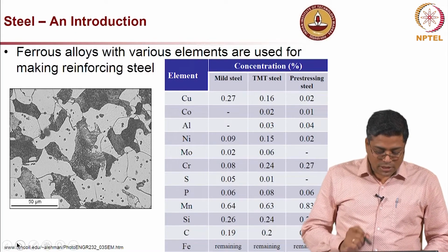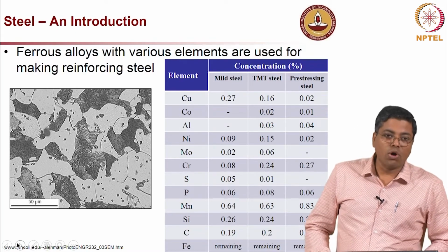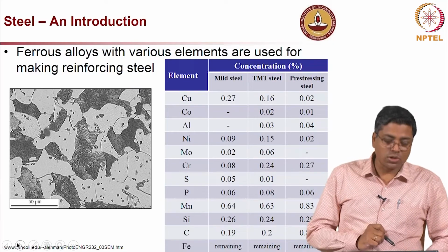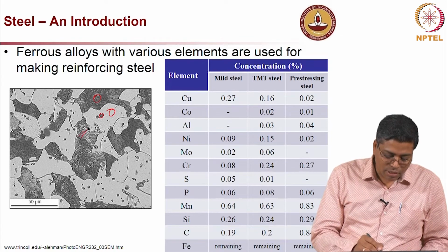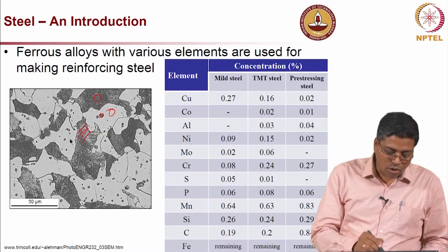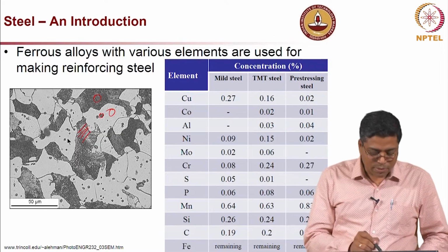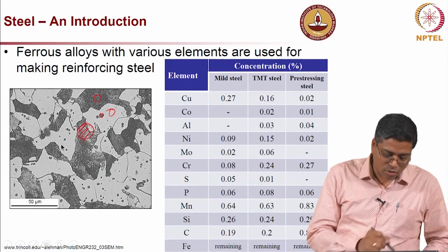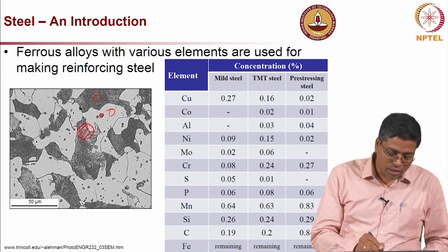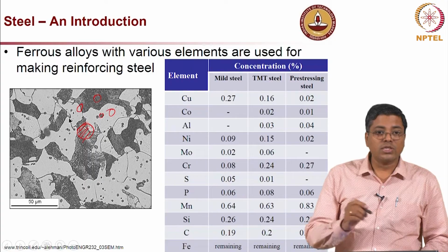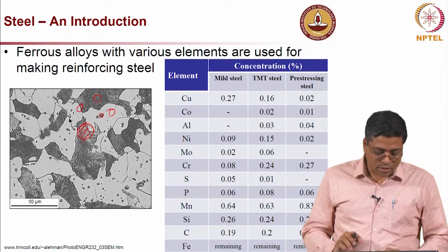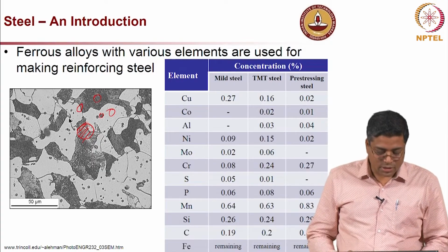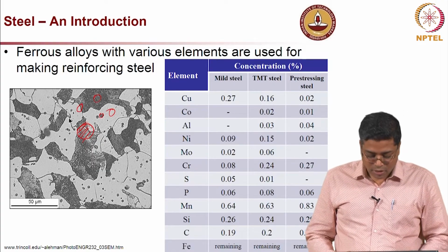Now, when you look at steel, usually we think it is a homogeneous material, but if you look in a microscope, this is how it looks. So, you have these different phases in the same steel, and you can see some lamellar structure here. All of these lead to some kind of local corrosion cell in between. So, one of the phases might be corroding in preference to the other, and that is what metallurgists like to modify so that we can have better quality steel.